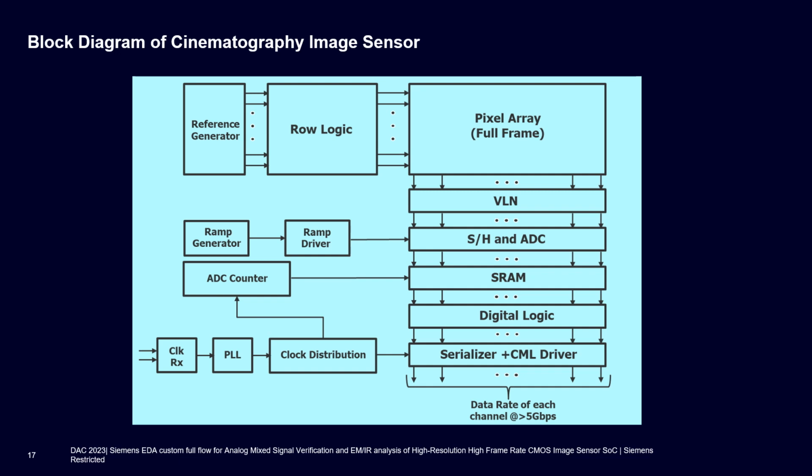We provide a 50 MHz differential input clock to the chip, which is received by the clock receiver on chip, which generates a 50 MHz CMOS reference clock for the PLL. The output of the PLL is a greater than 2.5 GHz high-speed clock signal, which drives the serializer.